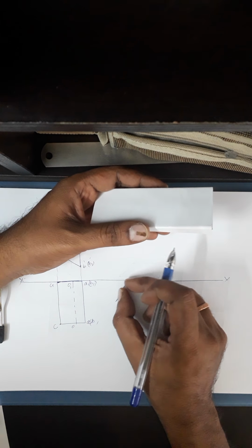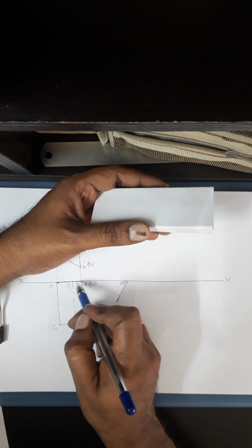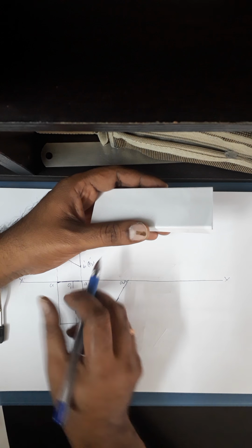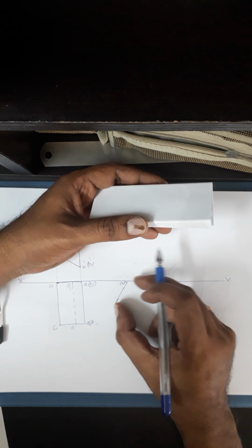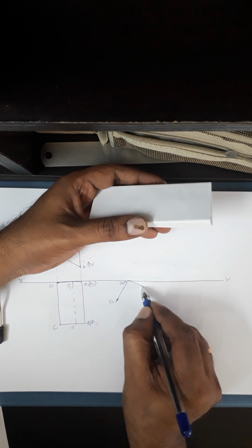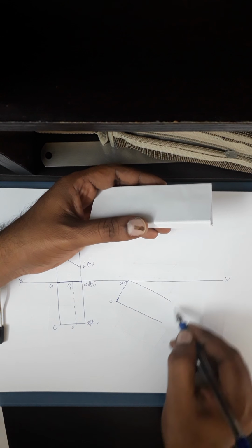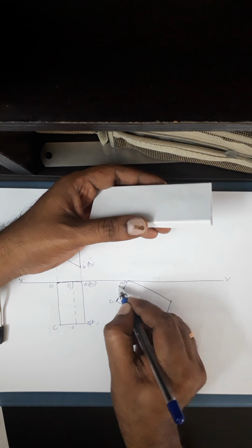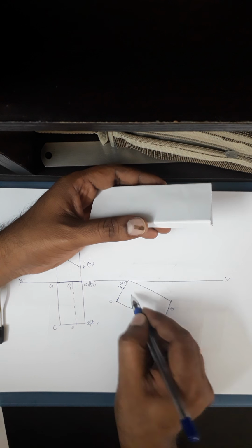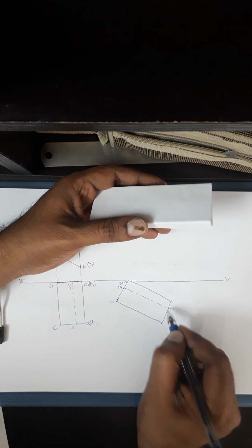So I'll take this length. This is A1, B1. I'll take this length and mark it here, just transferring using a compass or divider. Then I'll take the complete length, and I can get that point C1. Then I'll go for drawing this now. I'll redraw the same view. Axis O1. So this is O, big dash, small, big, small, big, small.